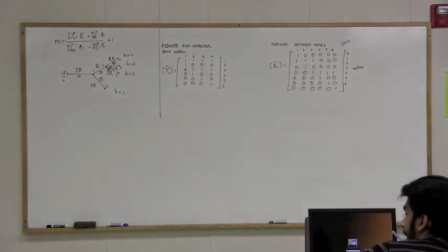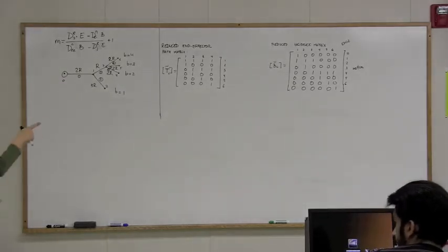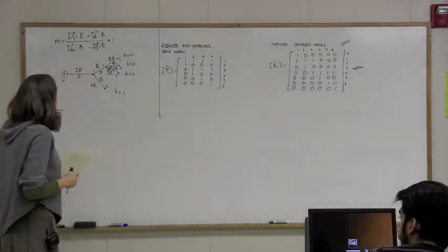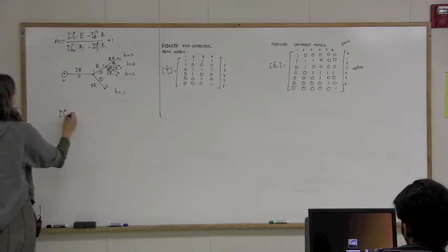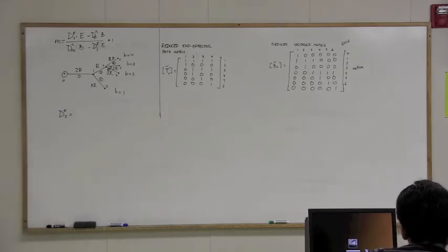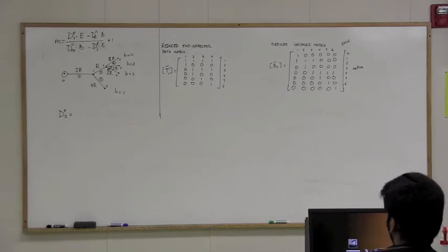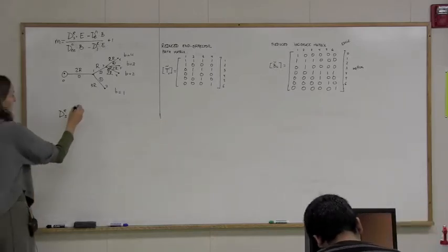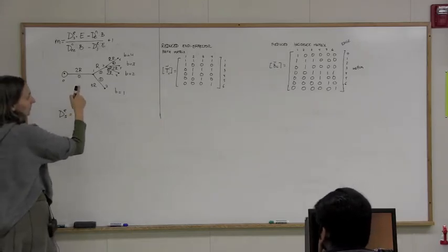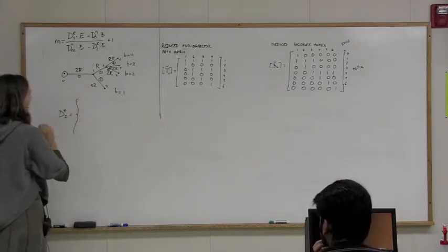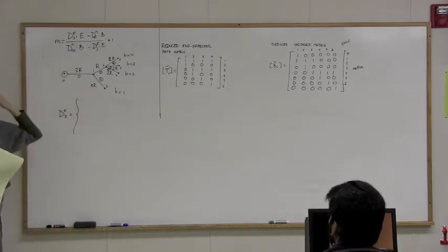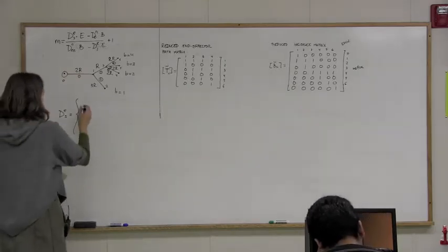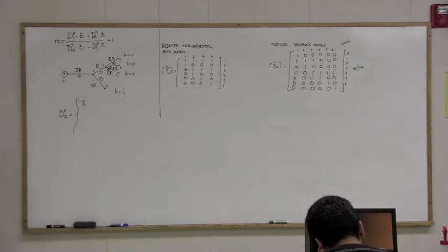All right. Now we need to start working on those matrices. We actually use this later, and I should use it today. Let's start computing these vectors. D, E, S, that was the number of structural parameters per edge. How many edges? 6, so this will be a 6 by 1 vector. The first edge has 2 revolute joints, which means 8 structural parameters. Each revolute joint is 4 structural parameters, and we are counting just the independent ones.